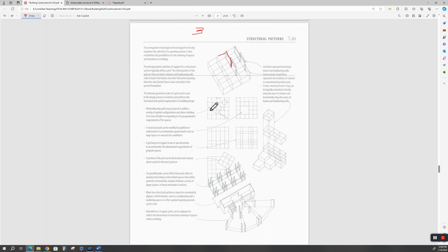What if it's a big auditorium for a concert? Well, you've got your stage, and then you've got all this seating down here. People don't want to pay for a ticket and have big old columns blocking them from seeing the stage. So again, if you start off with a basic grid and start filling in that grid, and something needs to be in this area, well, that can't be a column, right? So that means this span has to be bigger. But if it's a multi-story,